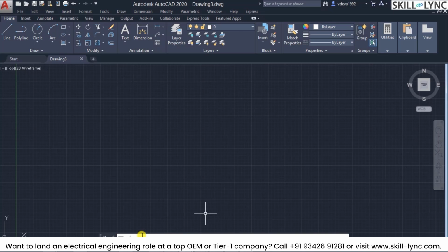So now we are giving an open parenthesis here in the command prompt, the command line, stating that I'm going to execute a list. So let us consider that you're going to perform a multiplication operation upon the operands, that is 2 space 5, and then close the parenthesis and click on enter. You can see that AutoLISP executes that as 2 times 5 is 10. So this is how you execute this command in the command line of AutoCAD.